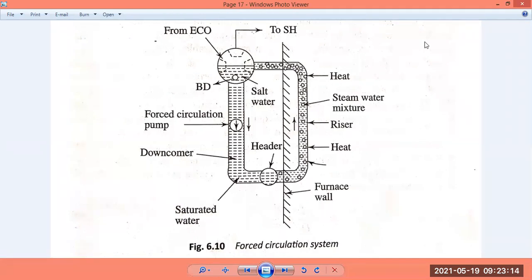So what is going on here? If the rate is not sufficient to carry the heat away from the furnace, the furnace will heat all these riser rods and riser pipes much more than their capability of taking heat, leading to their overheating and ultimate rupture, when the tube temperature exceeds the melting point of the metal itself.